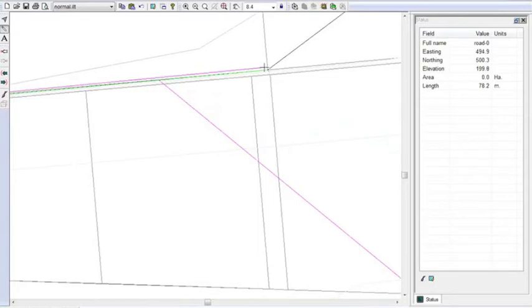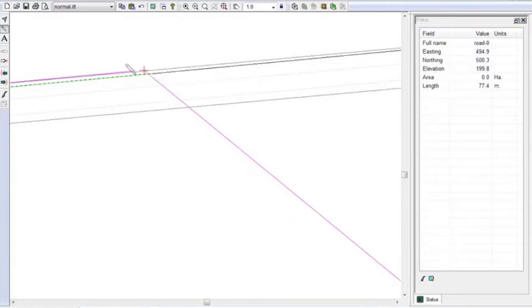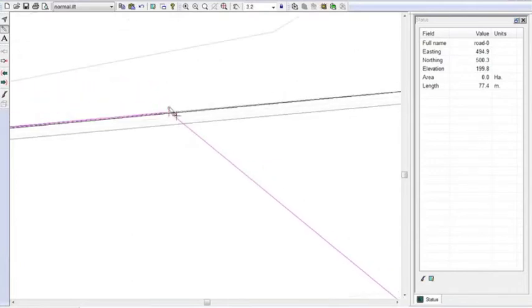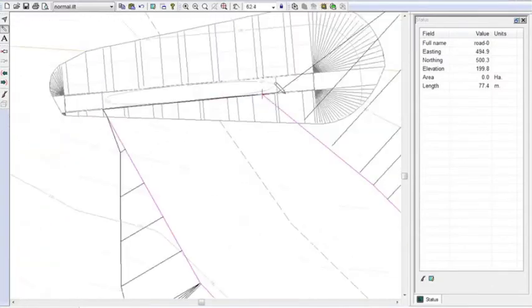There's another point out here I want to get rid of. That one, and snap it back to there. I think I snapped it to the wrong elevation. I want to snap it up to 200 there. I haven't got background snap turned on. That was a mistake. Is this a problem? I don't know. Let's just leave it the way it is. See what it does. So I'll recalculate the grading operation.